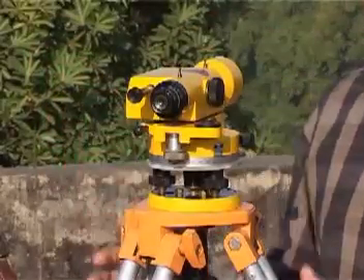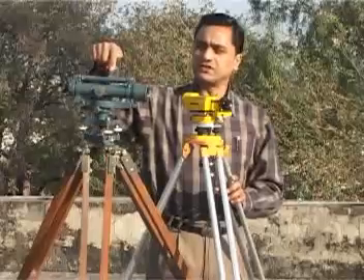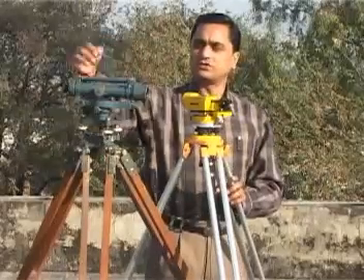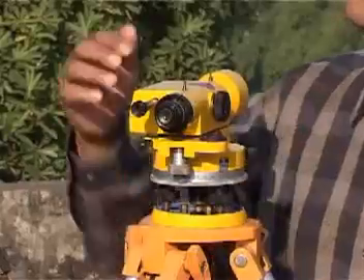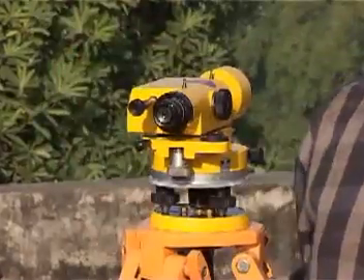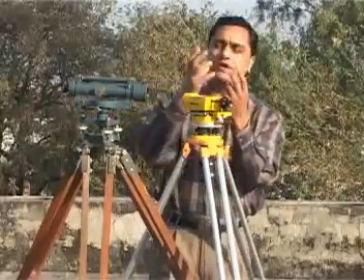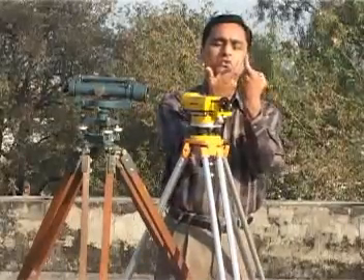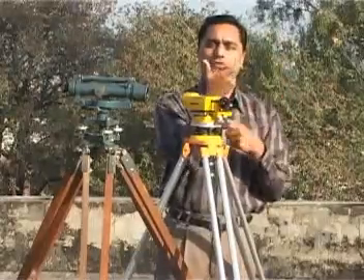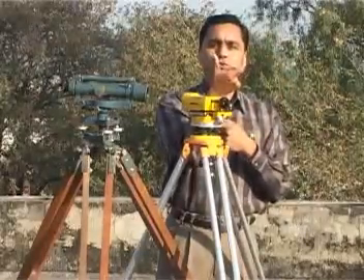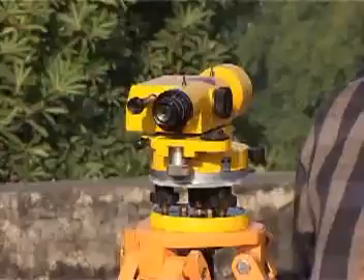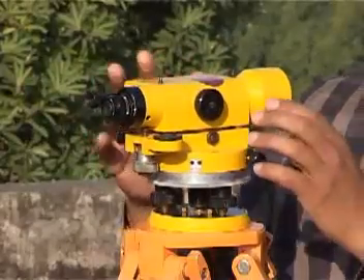There are different kinds of bubble tubes. One which we see in the dumpy level, which we see externally. Here we see the bubble tube which is internal, and this internal bubble tube makes a U. There will be 2 U's and they will move about, and once it is one full U, then this is leveled. Well, how do we do that?